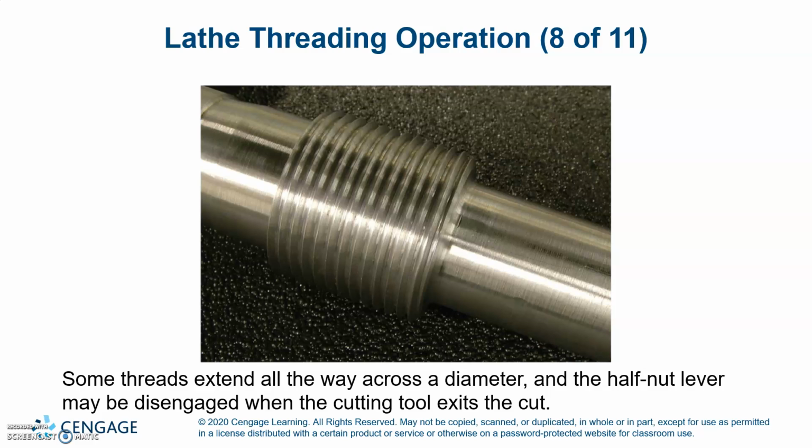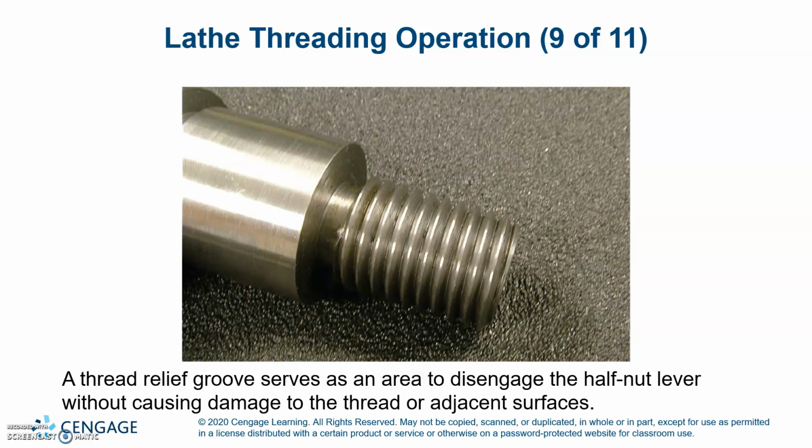Some threads extend all the way across the diameter, and the half nut lever may be disengaged when the cutting tool exits the cut. A thread relief groove serves as an area to disengage the half nut lever without causing damage to the thread or adjacent surfaces.